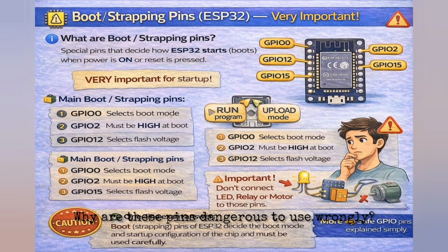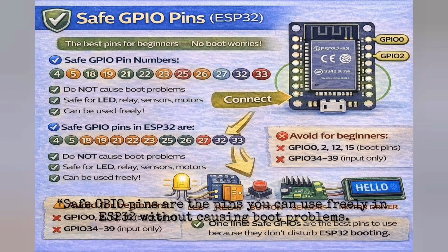Why are these pins dangerous to use wrongly? If you connect LED, relay, motor to these pins, they can pull the pin high or low and ESP32 may not start at all. Safe GPIO pins are the pins you can use freely in ESP32 without causing boot problems.